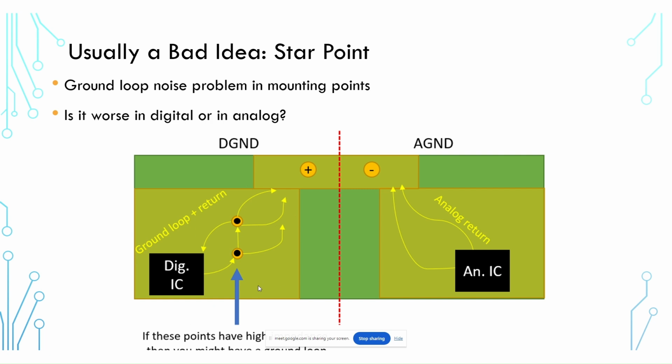But I think ground loops are greatly overly exaggerated in PCBs, except in certain instances. That's something worth talking about in a session on EMI, because it's really an EMI problem. It's also a problem that arises when you have a system that has to connect with earth.